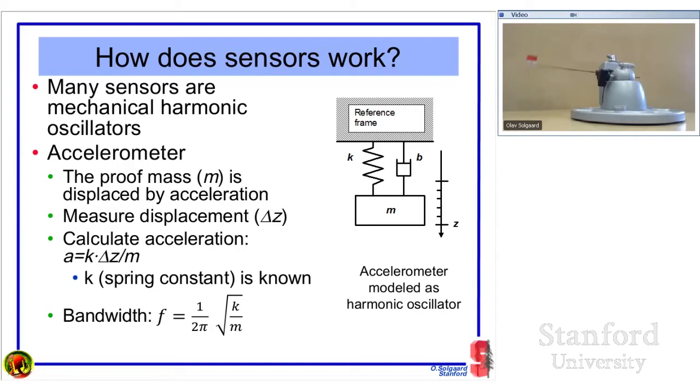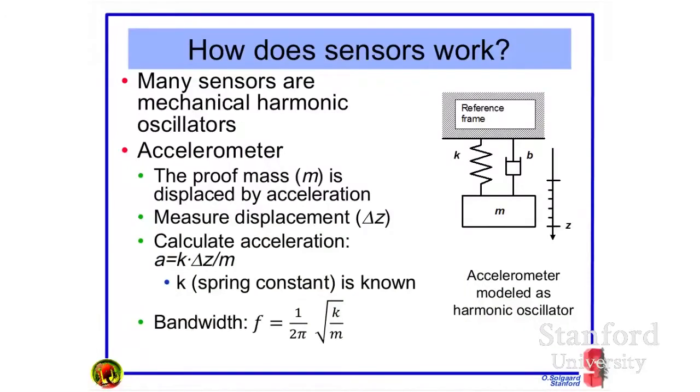If you now switch back to my slides here, we can see that what I showed you is essentially the system that I showed here, as a figure. There is a spring, with spring constant K. There's a mass that's moving on it. What I didn't talk about was that there's some damping, but you can certainly see that the swinging didn't go on forever. It damped out. Maybe it didn't damp out fast enough. I'm looking at it over here. Now it's still vibrating, but the vibration goes down. So there's a damper.